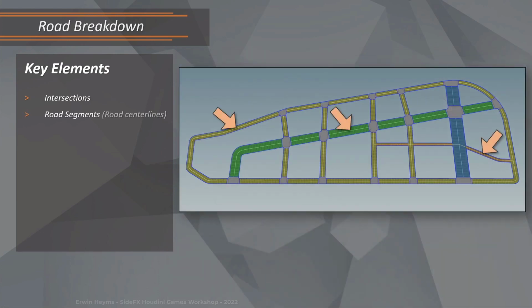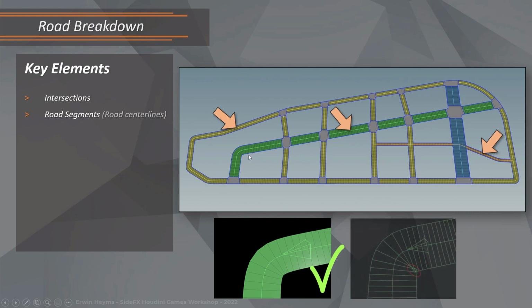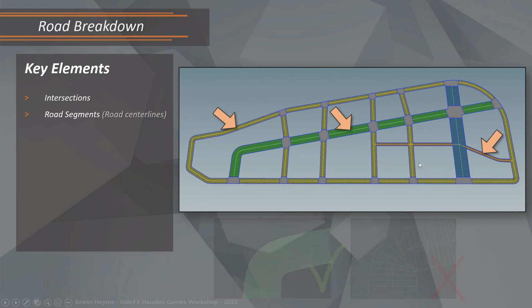Now next, we have the road segments in between. And in this case, they can round corners. So at the very least, I need to make sure that the corners of these roads have enough radius in order to allow the corners to exist properly, especially when the roads get bigger, when they get wider, right? Now, you can also notice that we have a couple of side roads in here. These don't create intersections. Instead, they connect directly to the sides of a bigger road, like the orange one does here with the blue road.